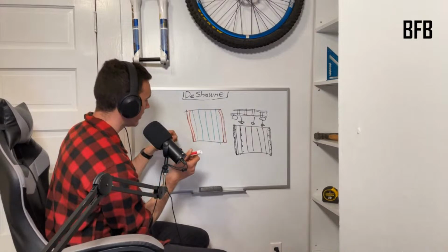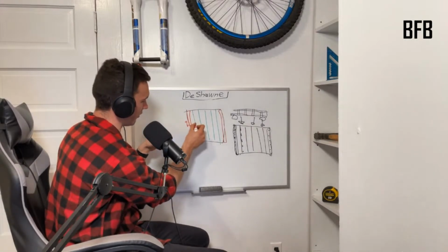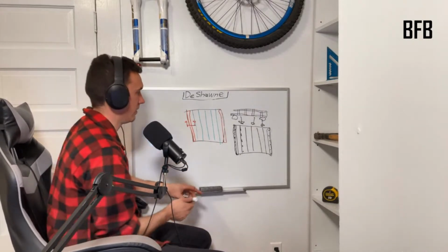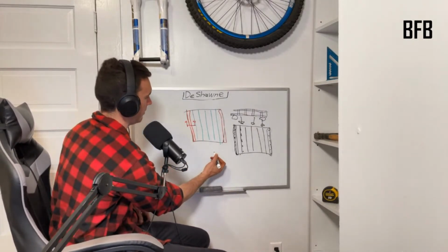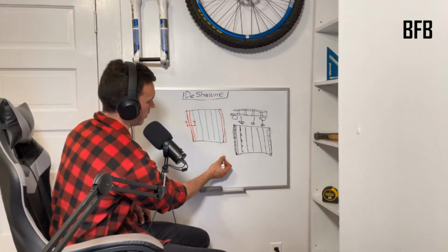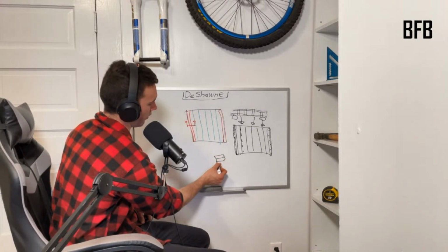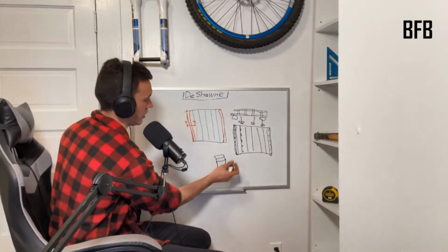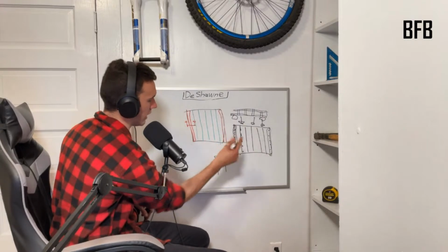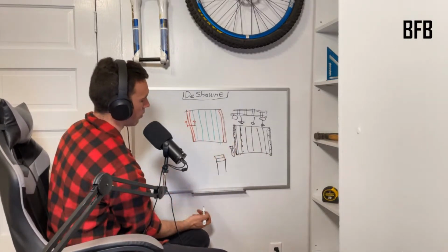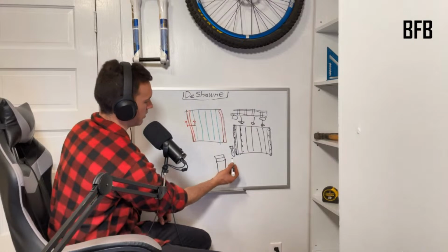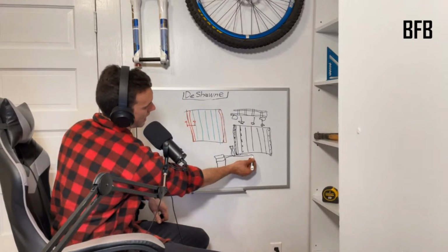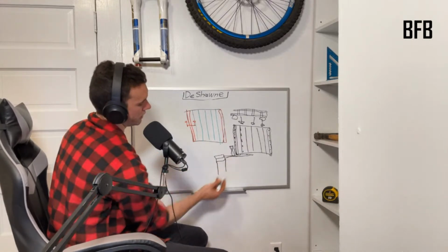Now, let me give you a little cross section here if you're not super familiar with framing. Okay, the cross section of this thing is going to be in black because that's easier to see, in honor of our whiteboard named Deshaun. So we're going to have two top plates in wall framing, and then there's your stud. This is the cross section. Usually like here at the ceiling joist thing, you've got a ceiling joist floating over here, going in and out of the board, right? But none over here. Well, what you're typically going to do is your sheetrock ceiling goes like that, right? It's connected to all the ceiling joists.